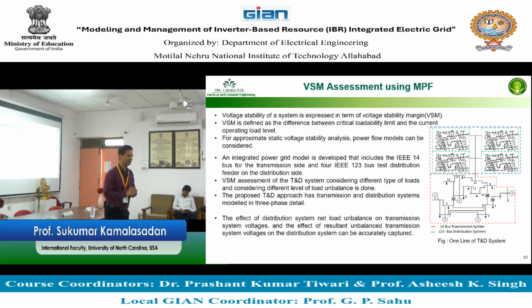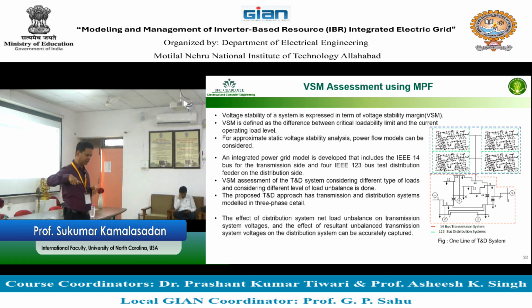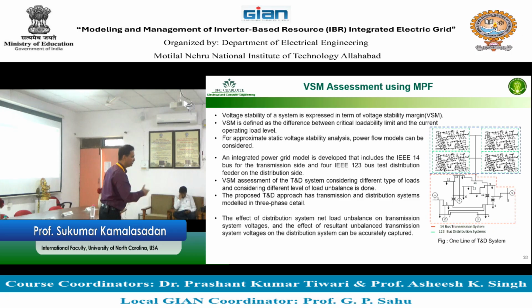I just gave a 10-minute crash course on stability. When looking at this kind of study, we can study frequency stability, angle stability, and voltage stability. But what is more important to connect distribution and transmission networks, as sir was saying, is to understand the voltage profiles of the system, not just at the head end of the substation.